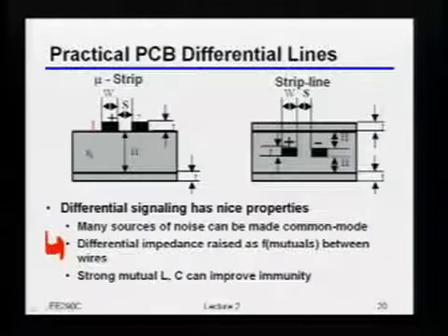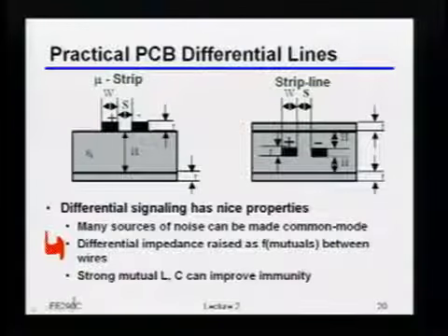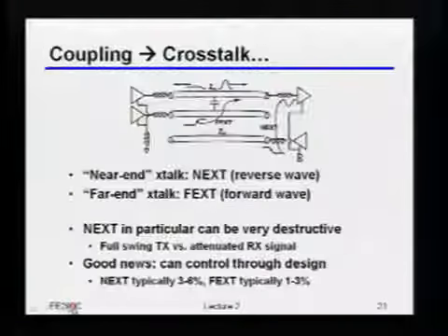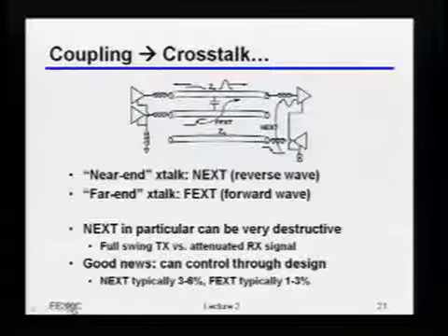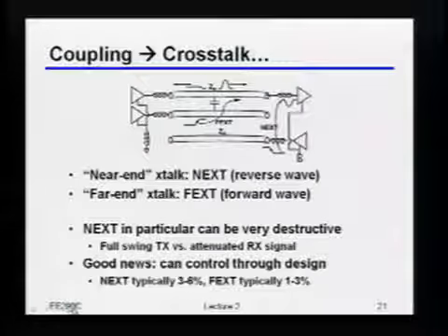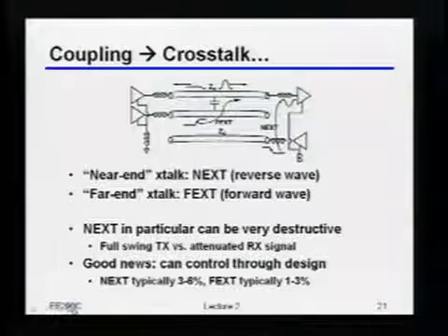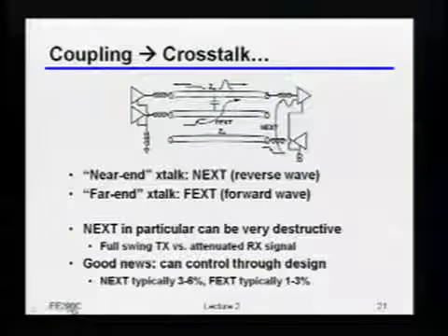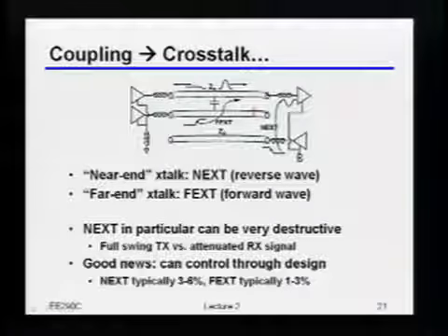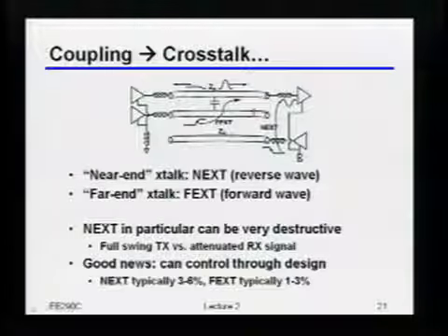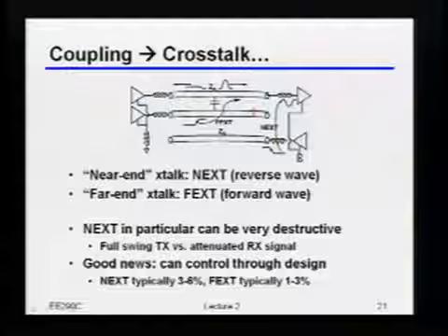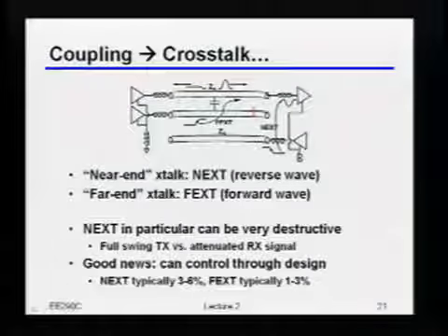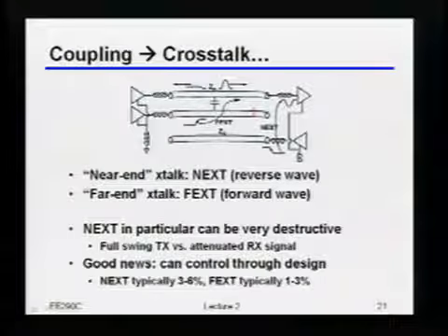Okay? So while I'm on that particular topic, if we really think about coupling, and we've talked about differential already, well, as we've said before, the bad news is that even though I have these nice wires all over the place, they can actually couple to each other, right? So even if I do a really good job and build nice differential transmission lines, if I've got other transmission lines around, they will couple into the things that you do care about. Okay? So just to give you a little bit of terminology here, there are basically two different types of crosstalk, and crosstalk obviously just comes from this coupling behavior.